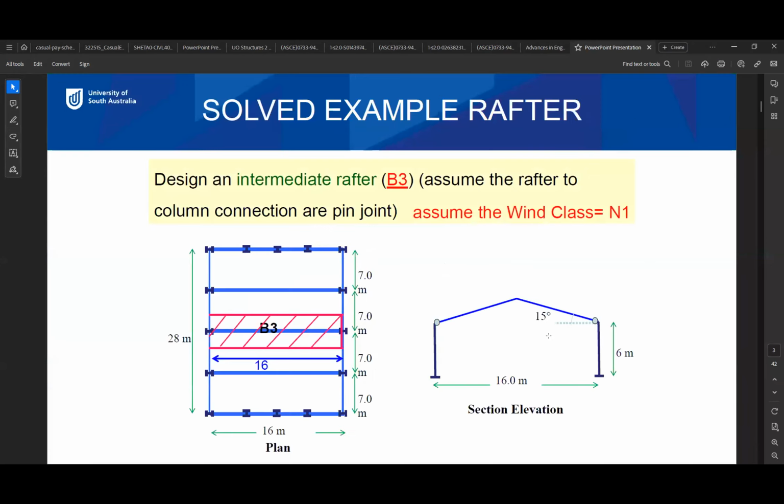So here, this is an example of B3. If you look at B3, the blue one here, it is similar to B1 you have in your shed. Just like two slopes, but your one is only one slope. But the same procedure for calculation is similar. So this is an intermediate rafter. This means that it carries half of the bay from top and half from bottom. So how much it carries, or the load width of this beam, is...